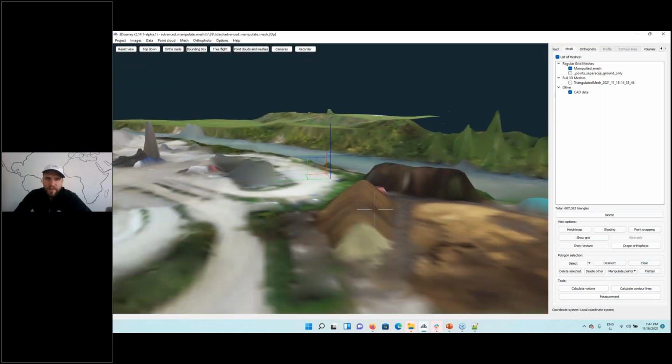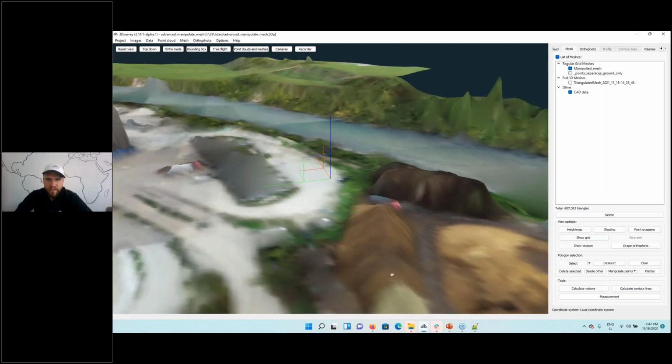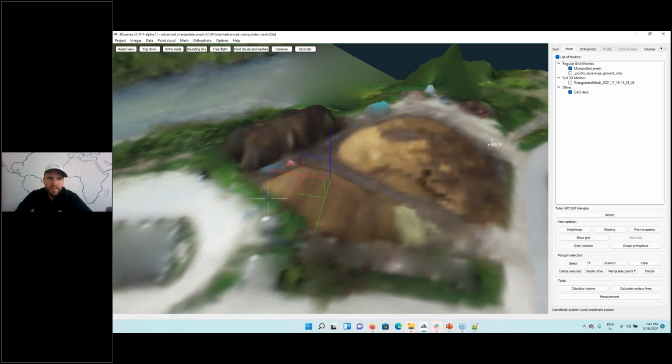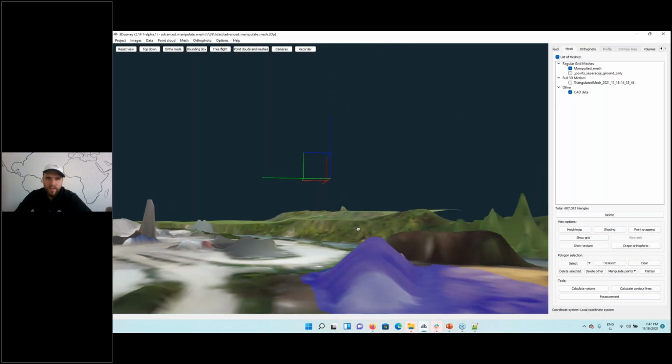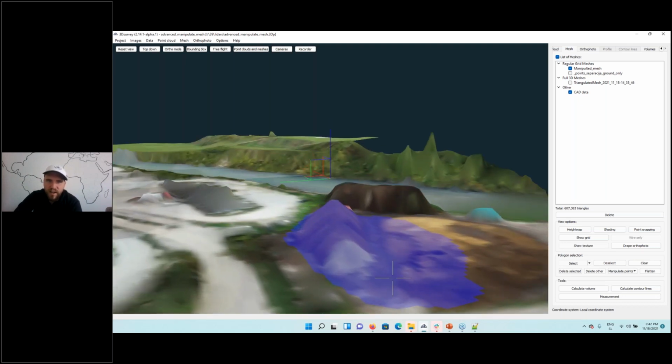So here we have a pile of material, and let's say we want to level our terrain. We want to make it flat. So we can say if this is our area of interest, and we take a steamroller and we make this area flat. We don't want to add or remove any material from the site. What height of the terrain will we get? So there is a function here under manipulate points. It is under average height.